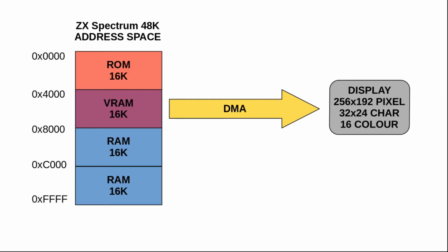But if I go on to the next screen, and the 48K model, then if I take that over the top of the Z80 model, you're only accessing 64K for the 48K model. So the first 16K is the actual ROM of the 48K Spectrum. Then you get what they call the VRAM, which is the video RAM, and is used to display stuff using DMA.